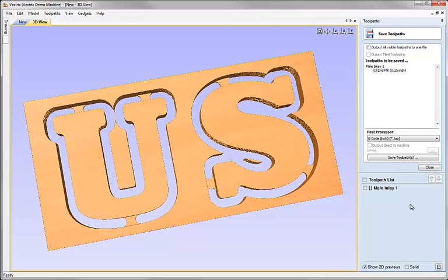As I mentioned before, there could be some benefit to cutting that first, because after we've machined this, we could go ahead and machine the oval part that we created, and as we machine the pockets for that, we could check for fit with these inlaid with the male inlays that we'd already cut. So at this point, we've pretty much concluded this particular tutorial.